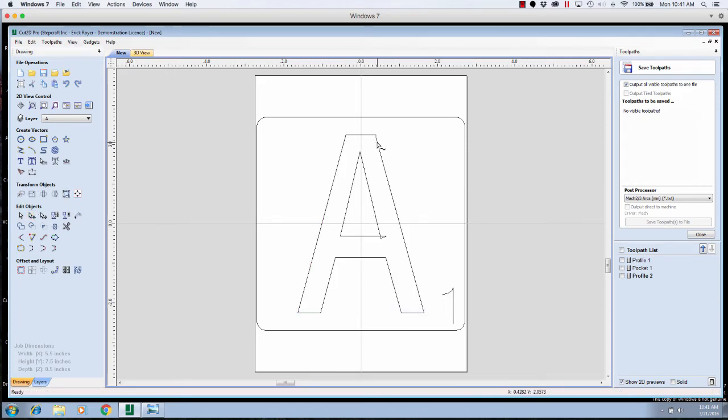So we're going to click on the A, we're going to click convert to curves, and we're going to node edit, and you'll see we've got an extra node there that we're just going to delete, and we are going to take this node and move it to the corner, and we're going to delete this one, and there's our A. Okay, so now keep in mind that if we're going to copy to another layer, we can't copy this because the A is no longer editable as text. It's now a curve. It's a regular node editable as far as lines and nodes, but it's not an editable text. So you'd have to go back and grab the F and then copy to make the other layer.